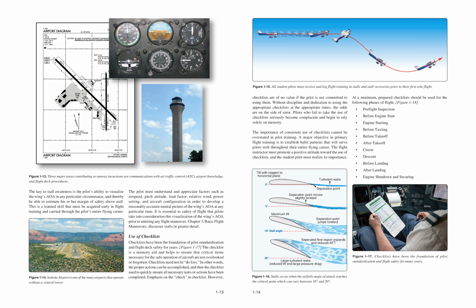Tilt with respect to horizontal plane. 0 degrees. 5 degrees. Turbulent wake. Separation point. Separation point moves slightly forward. Maximum lift. 16 degrees stall angle. Separation point jumps forward. Separated flow region expands and reduces lift. 20 degrees. Large turbulent wake. Reduced lift and large pressure drag.